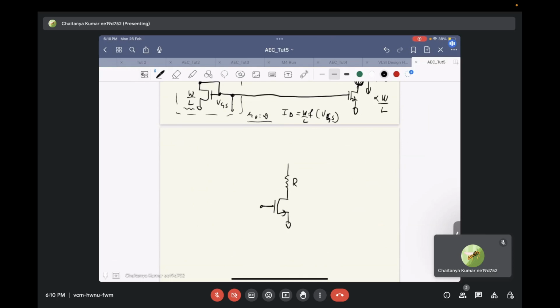So in this common source amplifier, we can connect this through a current source. So we can use this VGS directly connected to the gate of the common source amplifier and give our input through a coupling capacitor, and take our output over here.